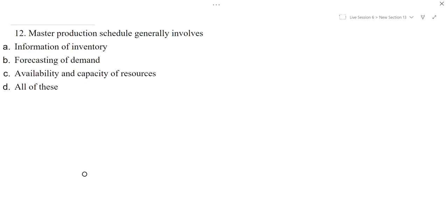According to the quantity, we decide whatever input materials or demand dependent items are required in the form of raw material or semi-finished product, and when these items are required. Thus, we identify the quantity of raw material, items needed, and the time when these materials are needed for smooth production, so that the production schedule requirement can be satisfied.